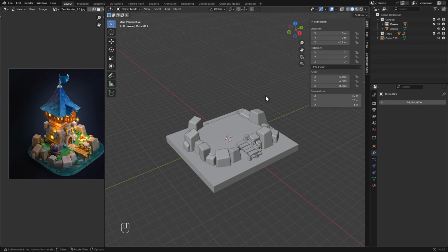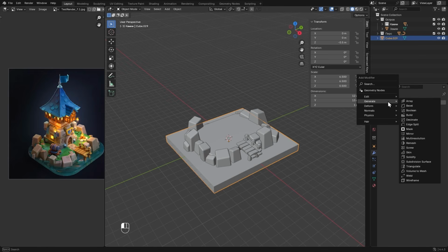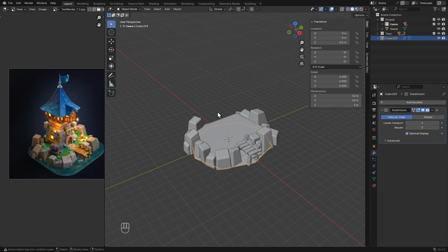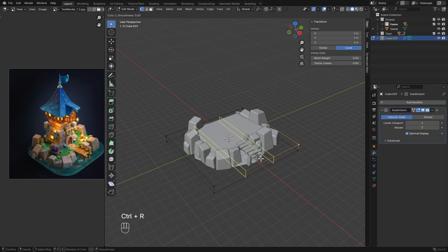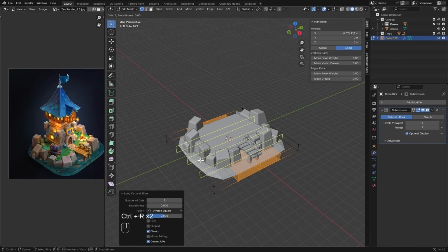Now we're going to learn a new modifier. I select the object, go to the Modifiers tab, and under Generate, look for Subdivision Surface, meaning subdividing the model. Our object has become like a pancake. Now I'll enter Edit mode, and we'll notice that its shape actually remained the same. The modifier simply relies on the vertices as key points and builds a new topology from them. The more of these key points vertices there are, the more defined the shape is.